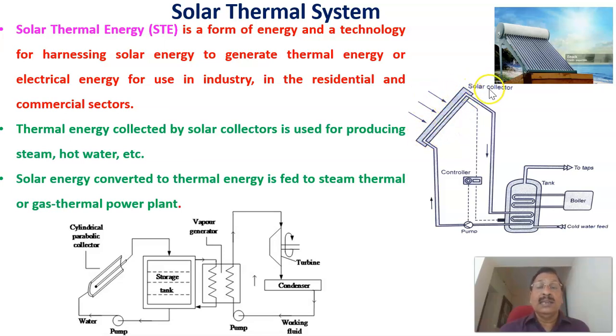That is done by this collector, a flat type collector. In that one, there is a heat transfer fluid that is passed through this. That thermal energy is transferred to the heat transfer fluid. There's a pumping mechanism with control, and the heat transfer fluid is flowing like this, and that heat is transferred using this setup, or heat exchanging mechanism. Here, cold water is entering, and because of the heated fluid here, the cold water is getting heated and we are getting hot water at the output.